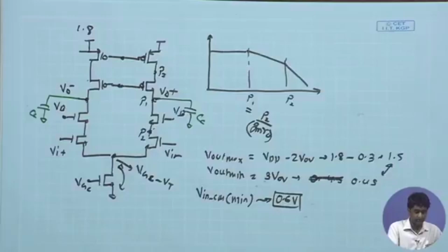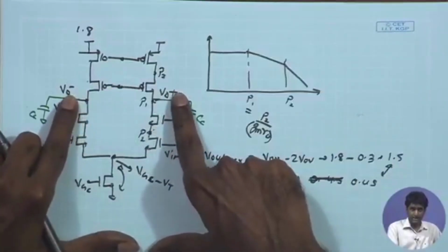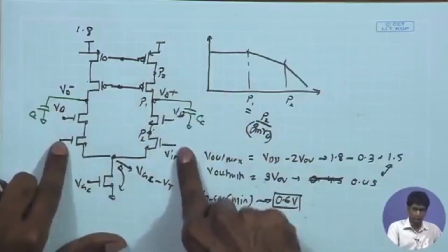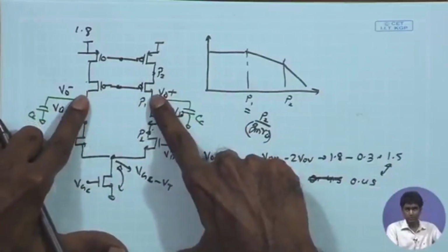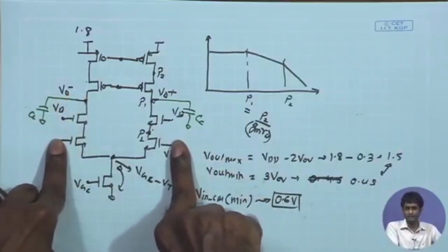On the other side, the negative points that you have are the limitations on output swing, and more severely the input biasing. How will you use the output DC common mode for maximum symmetric swing to bias the input DC?